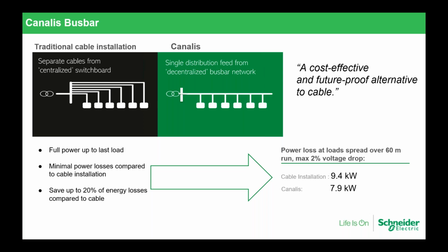You need to take this into account, not only the upfront cost, cable versus Busbar, but also the fact that you don't need maintenance for the Busbar, which would mean another cost if you're putting cables. You have a cost-effective solution with the Busbar because you have less power loss, and this means less cost on the energy bill because of this difference in power loss.